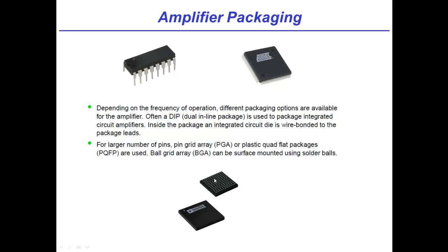And then there's another class, called the ball grid array, which has on the underside tiny little metallic regions, which are also solder paste or solder bonded onto the top flat surface of a printed circuit board. And there's a lot of these. There's lots of families and variants of these various packages depending on the need. And you can imagine as the years have rolled on and the density and the complexity of these integrated circuits has gone up, new families with very high density connections have emerged.